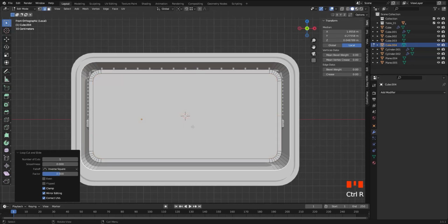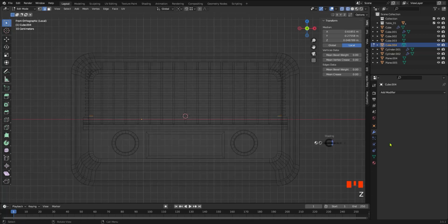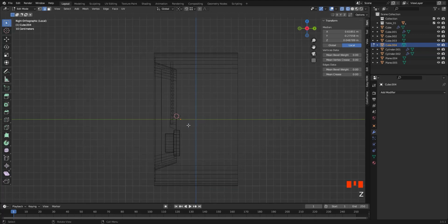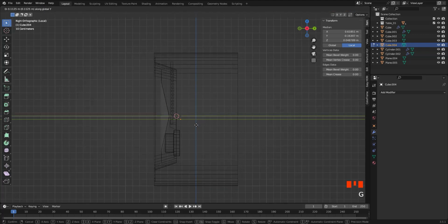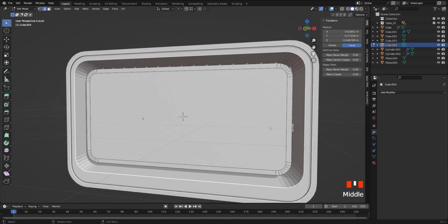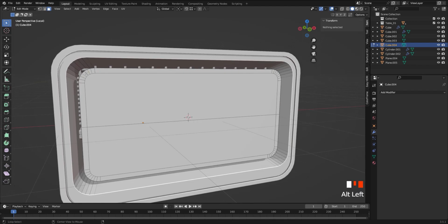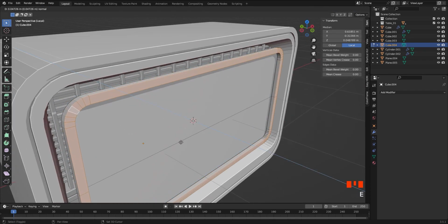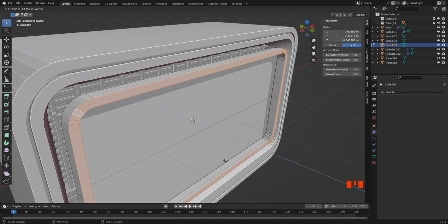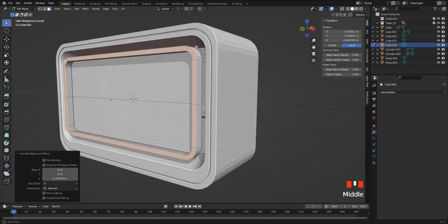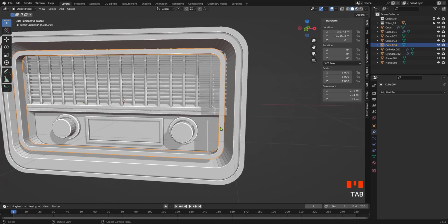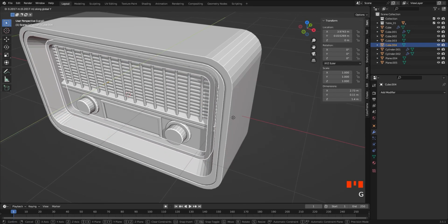Let's add a loop cut on this particular area as well. We can drag them in Y-axis. However, let's connect these two together. Pressing J will connect these vertices with each other. Extrude this area. Delete the middle face. Hold down G plus Y to push them back.